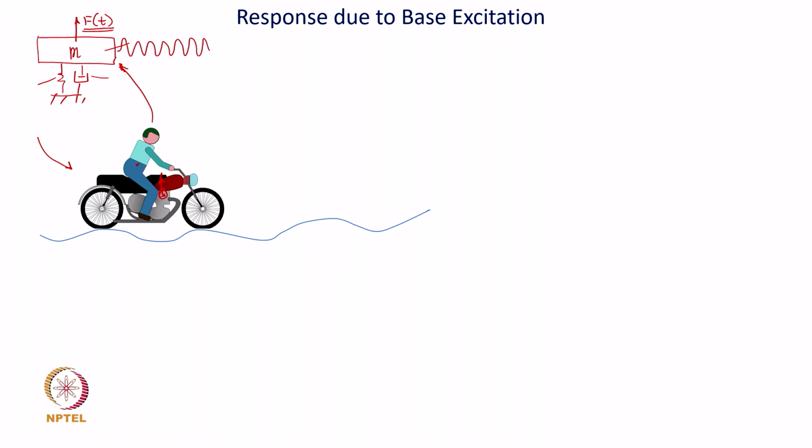Now, what we are going to look at is, supposing we ignore the excitation source from the engine or from any other excitation source on the mass. We only say that this vehicle is cruising without vibration on a level road, and then it suddenly goes through a wavy road. So, the road profile here is making this kind of a motion. I mean the profile is such that it is not a straight level road. If that happens, then what is the similar vibration response the chassis is going to generate? This is called base excitation, excitation coming from the base.